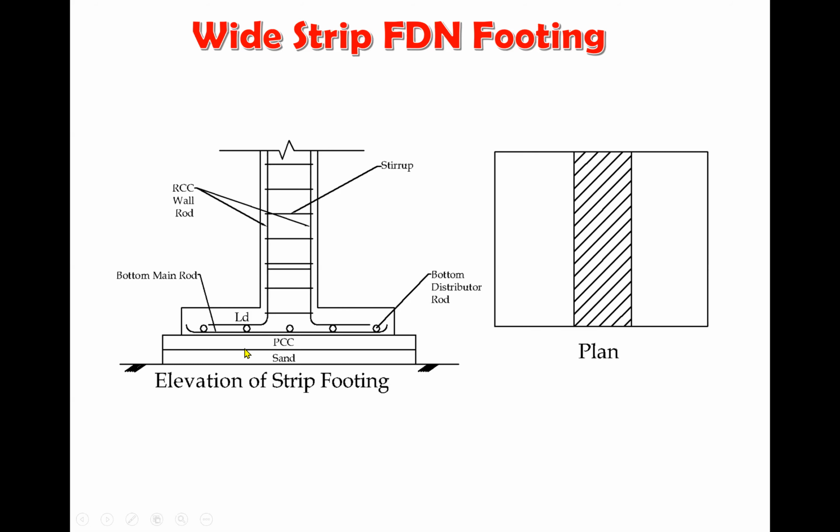So you tend to have some voids or pockets in those soils. So what you want is to have a broad surface to float, like how a boat will float on water, because you have a wider surface area, so it floats. So if we get those kinds of soil with a wider base, then even though you might have some pockets underneath, you can have this floating on top of that soil.